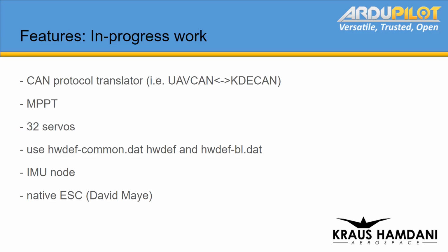Yeah, I mean, BLHeli is also open source on some of their systems. The BLHeli, yes, but that's in assembly only. I don't think we want to do an assembly-based ESC, and it's very hard to follow assembly. Yeah, I was going to say you'd have to see what it's doing, but you can't just copy and paste the code. I've looked through BLHeli_S, and it's really quite hard to follow. But the AM32 is written in C, as of course is VESC, so they're a better basis. Well, we're just starting the work on this right now, so I'm sure he'll see this video and have your great ideas and look into it further.